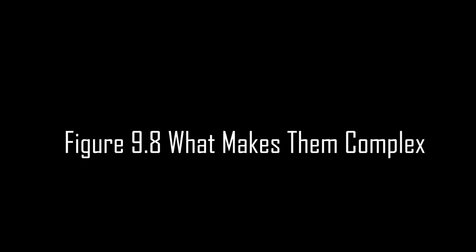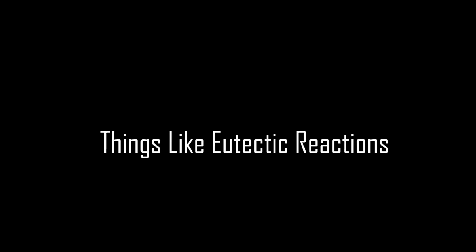What makes them complex? Things like eutectic reactions. That's where a liquid phase cools and transforms directly into 2 different solid phases simultaneously at a specific temperature and composition. Like a specific mixture freezing out all at once. Exactly. Lead tin solder relies on this.